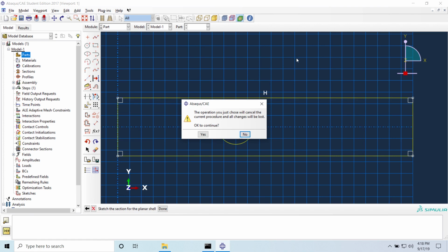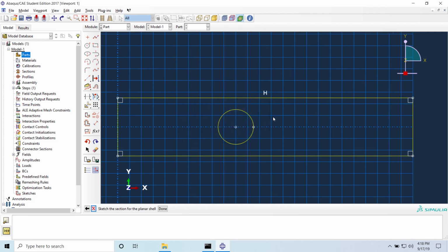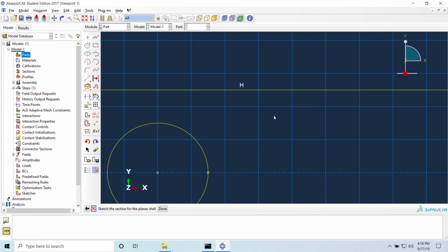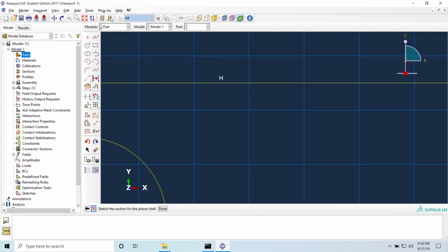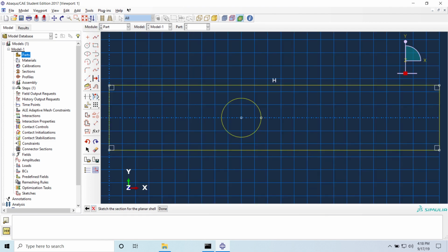When navigating across the plane, do you have to scroll out and scroll back in, or is there some shortcut key on the keyboard, instead of having to use a mouse? If you get lost at some point, then you can click this one, and it's gonna bring everything to the center. Okay, but if you want to move left to right... Okay, so for that, you have to hold Control and click the scroller, and then you can move.